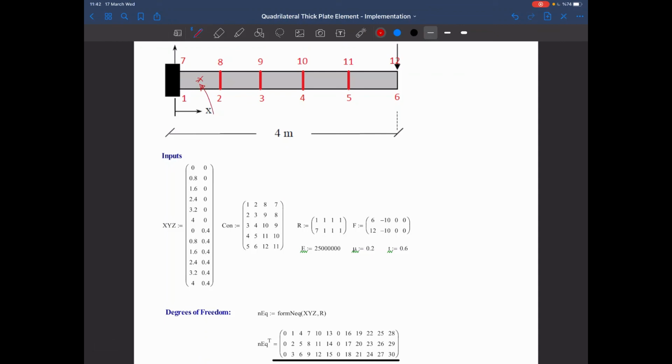So that's the main deficiency of this element. Yes, we sort of solved the locking problem. The locking problem was only solved for the single curvature, and the other deficiency of this element is that we only get a single moment per element, because the element has constant curvature through its surface. So in the literature, of course, there are many more elements that resolve these types of problems and improve the behavior of this type of thick plate elements.